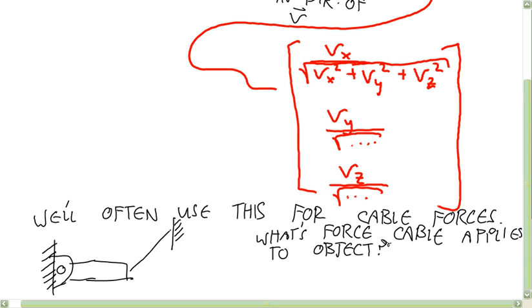Well, the cable is going to apply a force vector, right? So your first reaction might be to represent it as an unknown vector v, with an unknown x component and an unknown y component. But the problem with that is we know more than that about the cable. We know the direction that it acts. The only thing we don't know is the magnitude of that force. And so there must be a way to represent that unknown force vector with a single variable, okay?